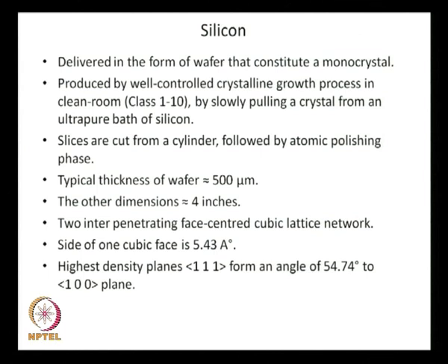All right. So, this is a particular feature which would be very important, because of the way the atoms are packed, when you take this silicon substrate for etching. After all, what is happening in etching? In etching, the silicon atom is reacting and the product is getting into the solution. So, if a plane is more packed with atoms, it would be more difficult to etch that plane, whereas if some other plane is less packed with atoms, that plane will be easily etched. So, when it comes to the etching of a silicon substrate, there would be an anisotropy developing within the silicon substrate.